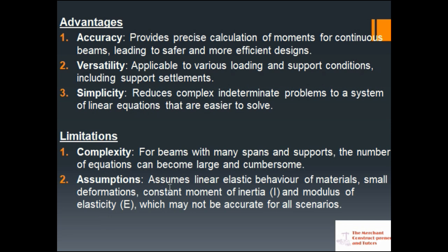So, assumptions. Now the limitation is that it makes some assumptions. It assumes linear elastic behavior of materials, small deformations, constant moment of inertia, and modulus of elasticity, which may not be accurate for all scenarios. We cannot predict that a material is perfectly linear elastic, or that the deformation formed based on the applied load is very small. But it gives you an approximate value that is accurate.